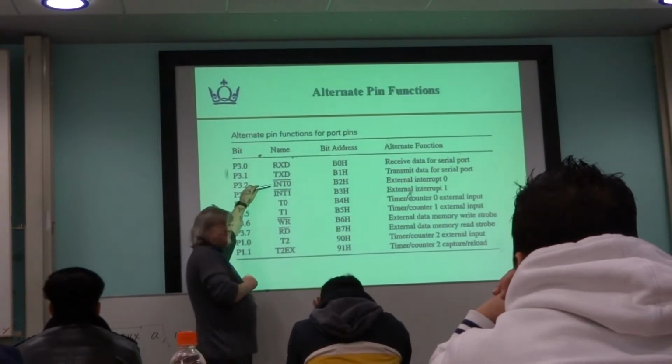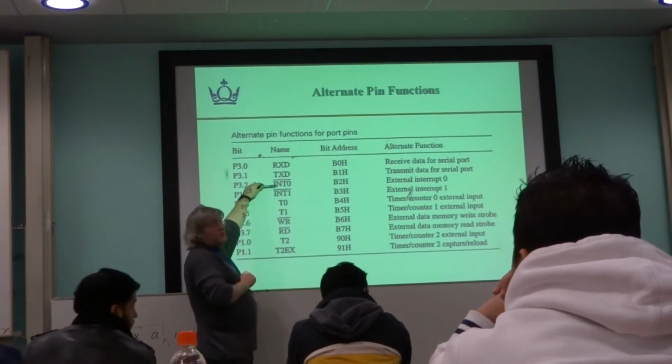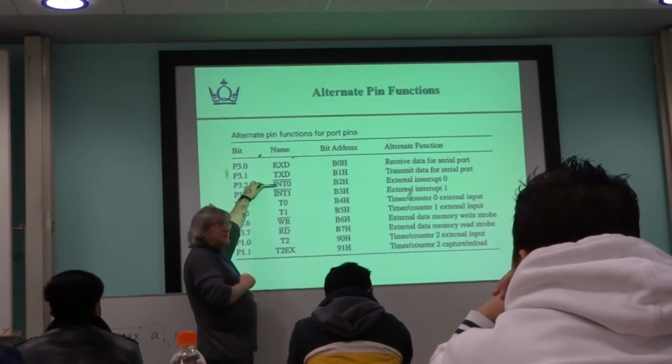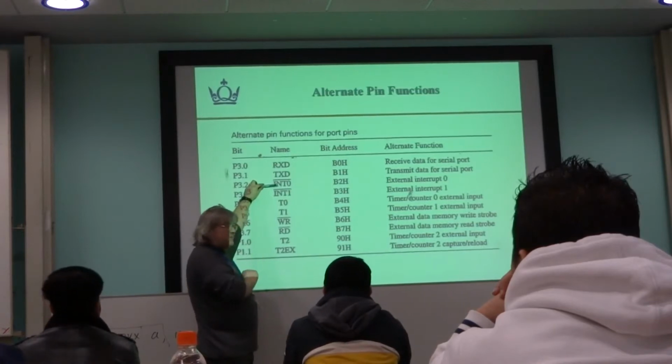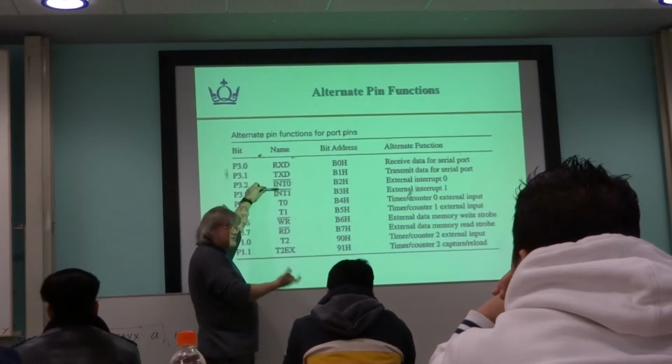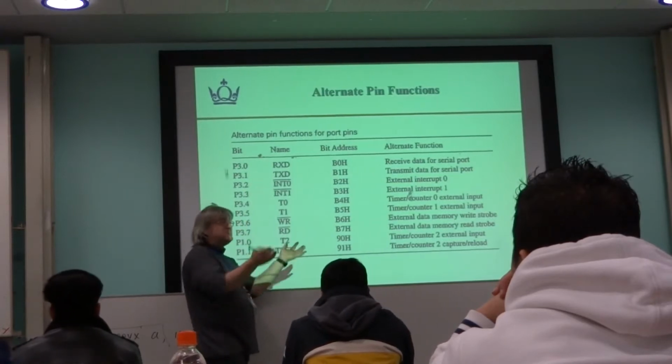No, it doesn't work that way. Effectively, you can either have what's called level triggered or edge triggered. If they were level triggered, when one of them goes, for example, low, the interrupt happens. If the other one goes low at the same time, you'll effectively cause 2 interrupts. One of them will have priority over the other one. It will do its job, and then the other one will be dealt with. But no, you can't demultiplex it into more.